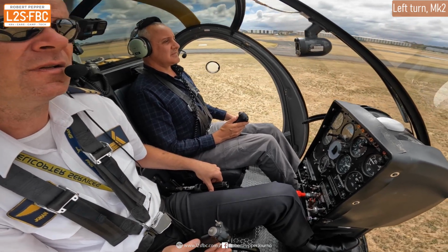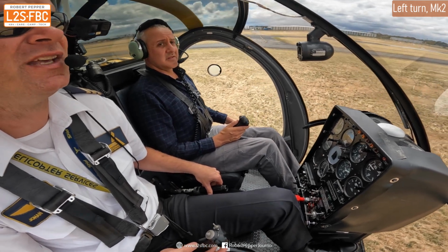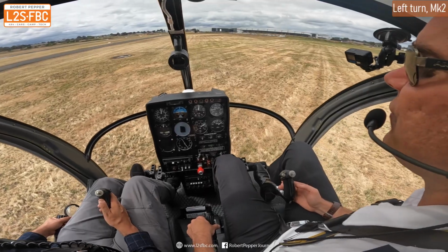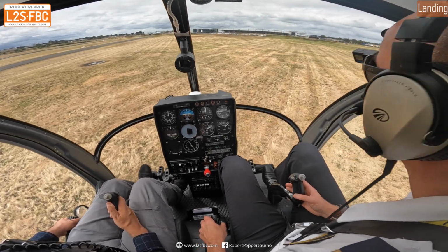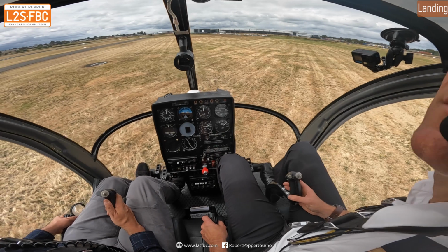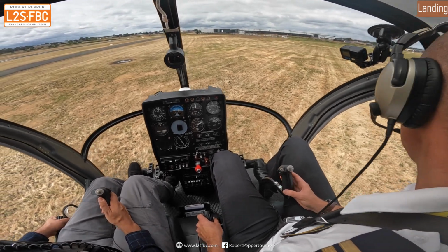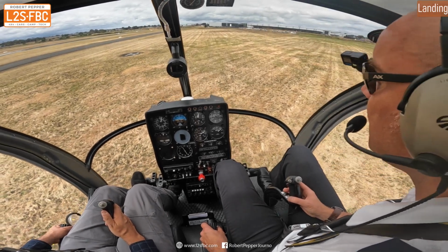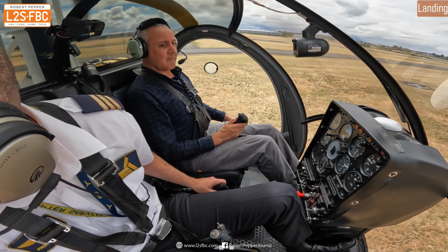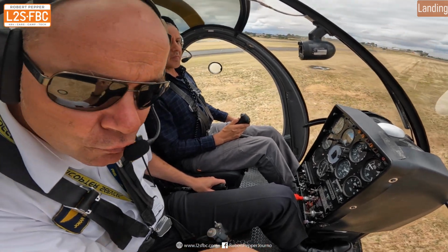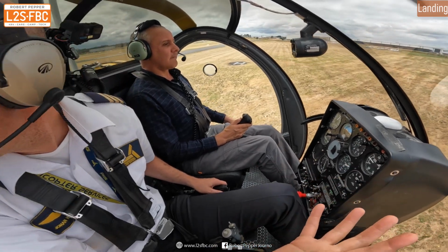So the instructor just said, do you want to have a go at landing? And I thought, okay, well that was a bit unexpected, but as an instructor I certainly wouldn't tell any student to do something I didn't think they were capable of. So yeah, let's give it a shot. The first thing he said is, all right, let's get it pointed into wind, which means a bit of a right turn, because that's obviously going to be easier to deal with. So sort of turn it round 45 degrees-ish and get vaguely pointed into wind, which is what we've done now.